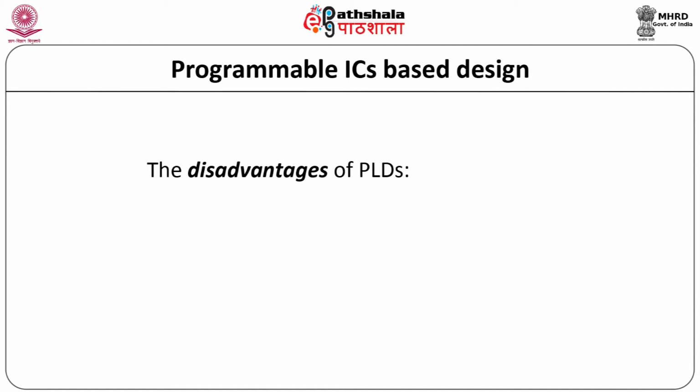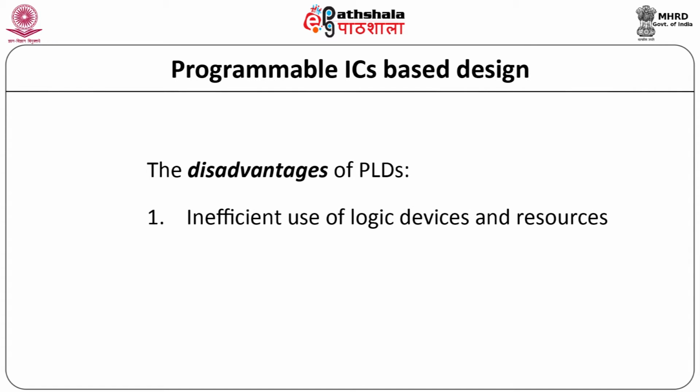Let us now discuss the disadvantages of PLDs. If the design involves fewer product terms, then the AND and OR arrays are not utilized to their full capacity. Therefore, we always say the disadvantage of PLD is inefficient use of logic devices and resources.